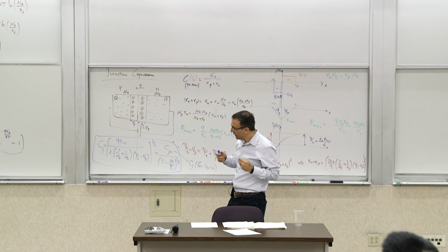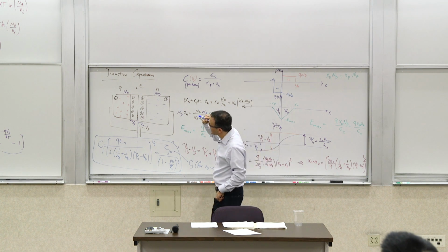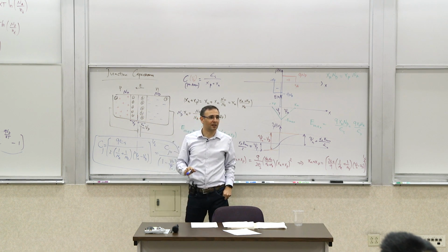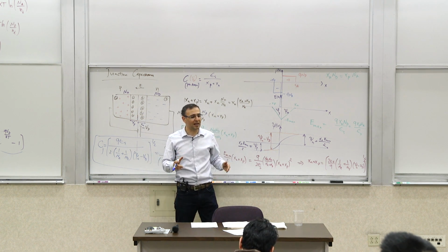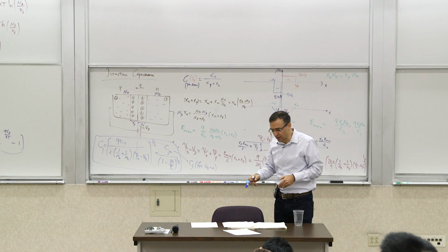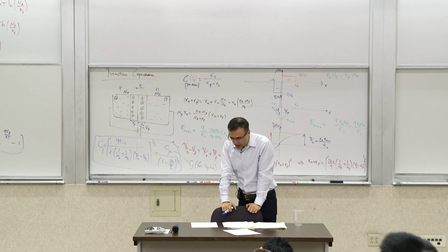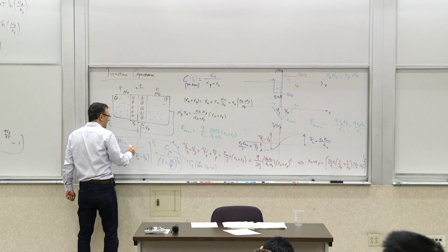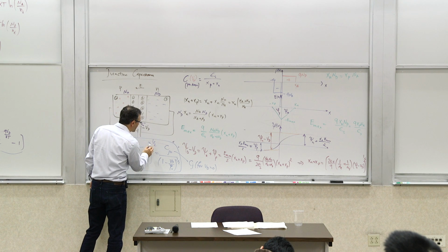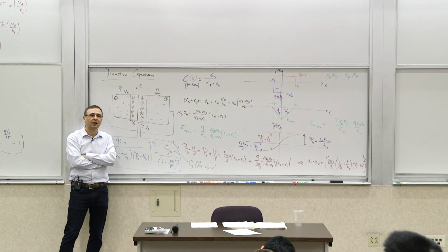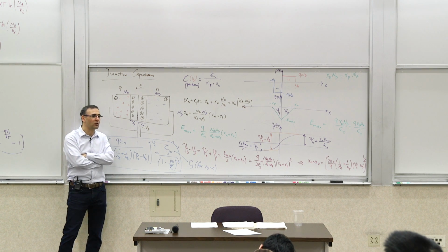But this is important. So the depletion region is dominated by the lightly doped side. If you want to make it narrower, shrink it, you need to make the concentration smaller. Now, this exponent, I have another question for you to think about. What dictates the value of this exponent? What determines that value? Where did that square root come from?